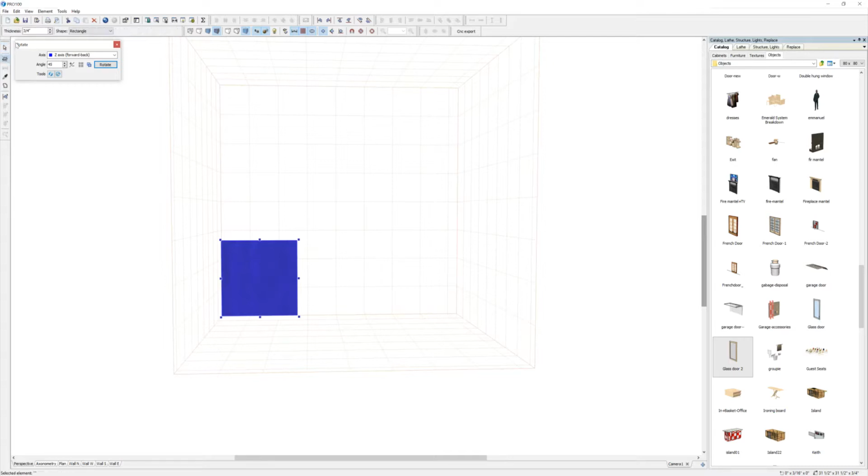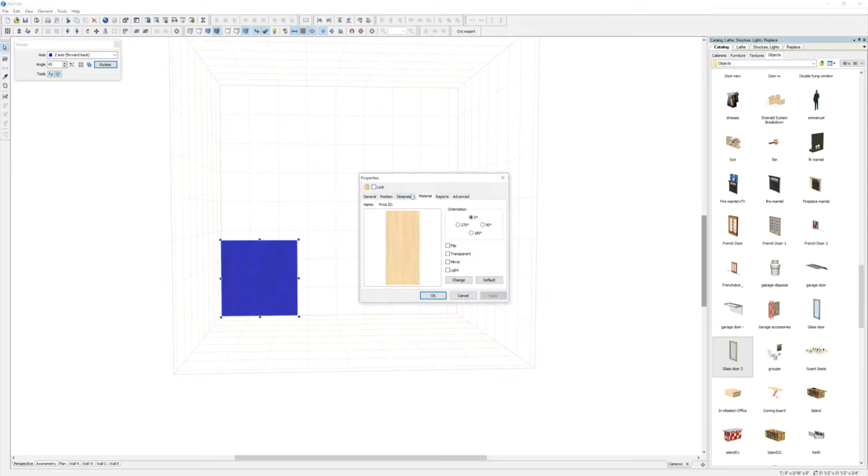My default, if you can see, it's 3/4 inch. So the first thing I want to do here is make my styles and rails. So that's easy. I'm gonna right click. I'm gonna make my styles 2 inches each. And I will lock it. So that's 2 inches, and the thickness is locked as well. You do not want to lock the height because you might be resizing doors. So we'll leave it like that.